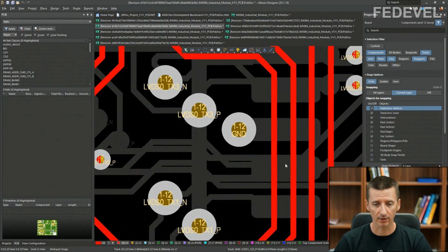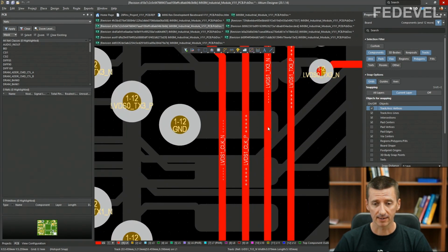This is one differential pair, this is the second differential pair, and the space between these differential pairs is even smaller than the space between plus and minus signals of the differential pair. This is not the way to route differential pairs. Differential pairs are usually really high speed signals. You really would like to keep a lot of space between differential pairs.